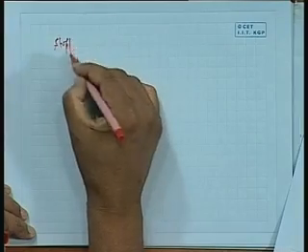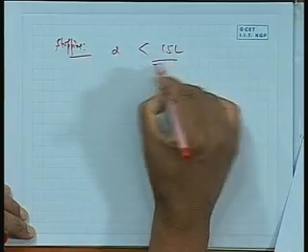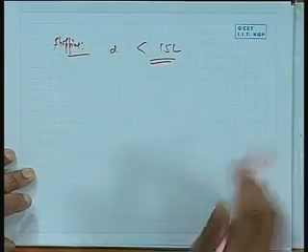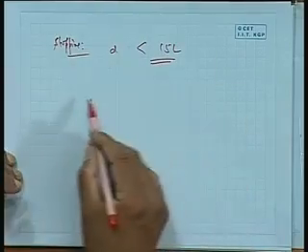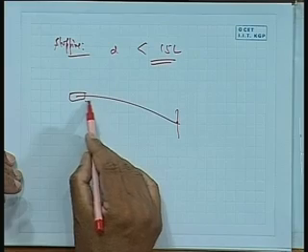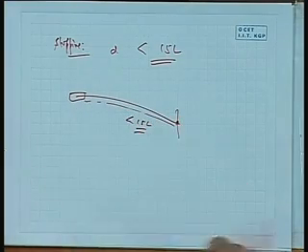And the last one is the stopping ability. I do not have so much time, but just to tell, there is a stipulation that the ship should stop within 15 ship lengths. That is all. The stopping ability is the final thing. This distance should be less than 15 L. This can be changed, etc. But basically, if the ship starts here, it stops here. The actual distance, where V becomes 0, should be less than 15 L.